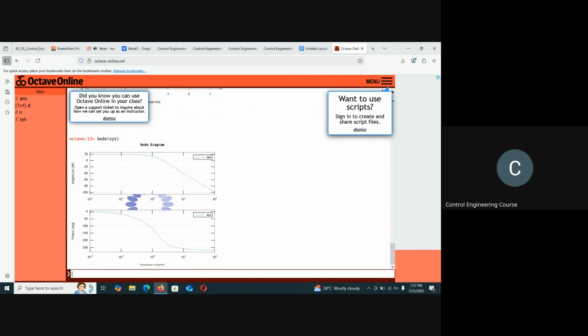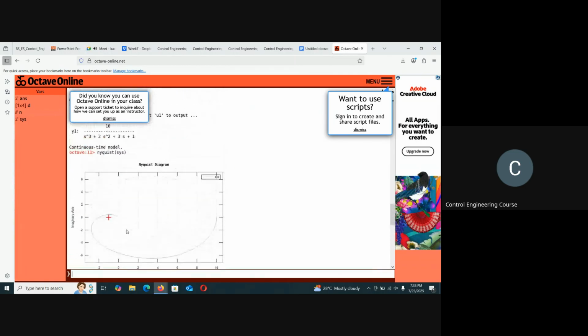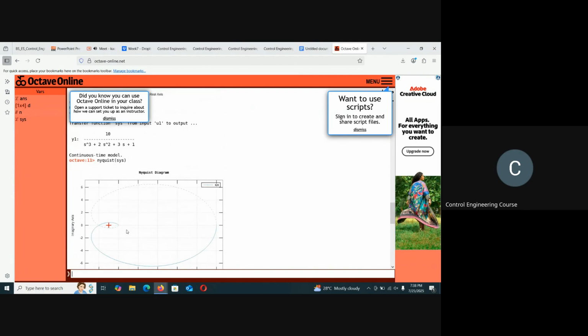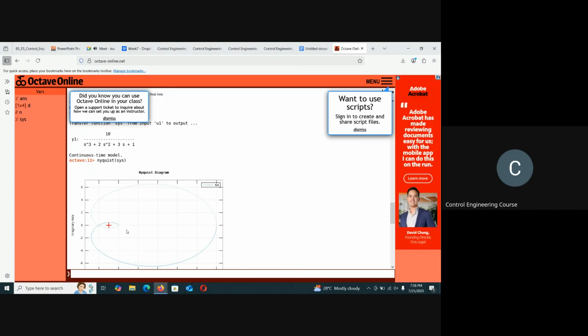Okay. So you have to learn to compare between root locus, Bode, and Nyquist. Comparative analysis you have to do, because not all methods are perfect. They are each easy in some situations. For example, root locus is very good if you want stability, but root locus will tell you about closed loop poles, but it won't tell you about closed loop zeros. So you have to simulate the system to actually see whether it's performing as you expect or not.